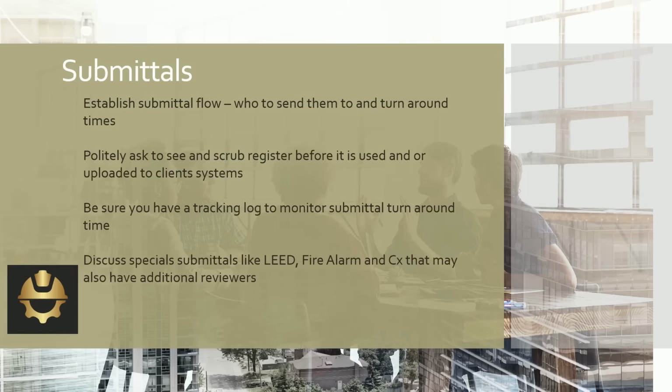So you've got to establish, your subcontractor sends you a submittal, let's just say it's finishes. And so you track it and you log it, and that starts the clock. If you don't determine, you send it to your design team and they take a month to turn that around, and then it's got to go to the owner for approval and they take a month, you're 60 days out from ever being able to order. Right. And so you've got to establish that right at the beginning of the project, or else it'll bite you. And that's how you're going to base your schedule for when you need to be requesting and when you've got to have those submittals in your hands.